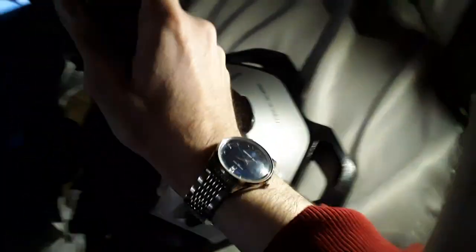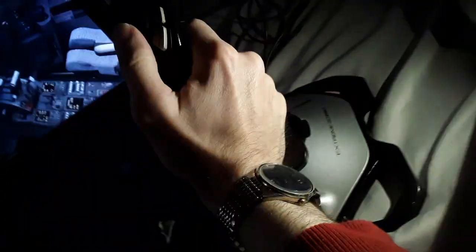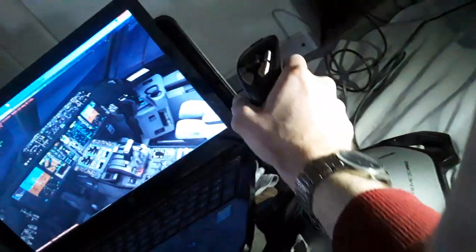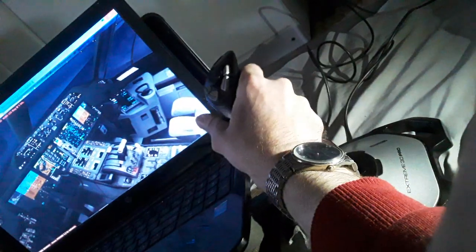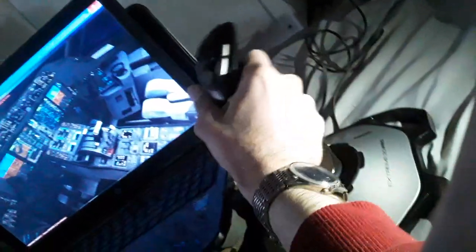I'm controlling the flight controls of the aircraft of the Boeing 787 over here. So you can see I'm having also this control. You can see both the captain and the first officer. We can climb and we can descend the aircraft like this, moving together both side sticks, both actually control columns and control wheels move together in the Boeing aircraft. In the Airbus you have the side stick priority of either side or dual input, you can choose between.